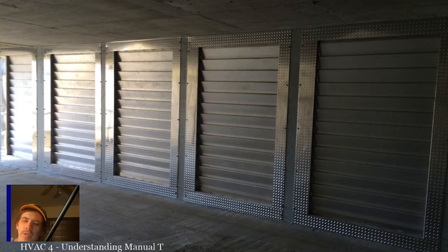So you'll think you found the issue when you open up the fire damper, but then you find the issue later on that caused the fire damper to close, because that fire damper will close at 160 or 180 degrees most of the time, and that is pretty close to a supply air temperature from a furnace. Supply air temperature from a furnace, 140 isn't outside of the realm of reason sometimes, 130, 140.